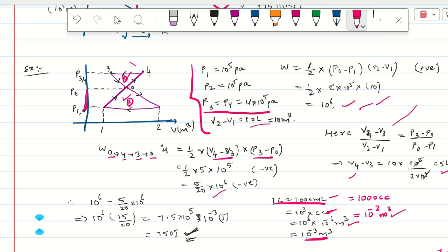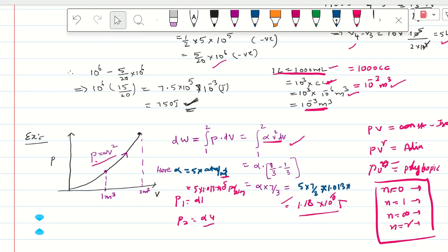So this is one type of model. And we are coming to the pressure changes: pressure equal to alpha V square. It asks us to find the work done. Work done means PdV, and P is changing here with the volume, right? For example, P may change with temperature, like beta T square or beta T cube. Then the T we have to change into V again.